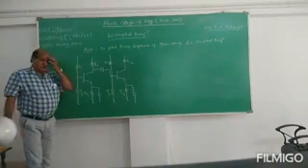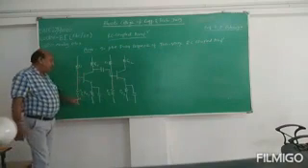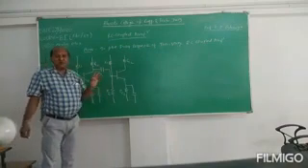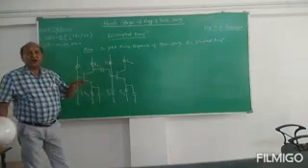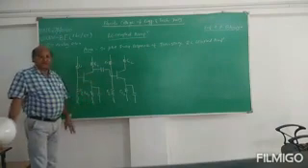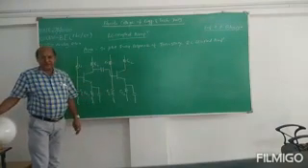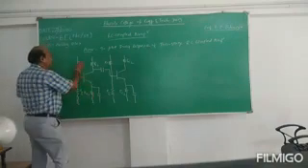So for practical use, R1 and R2, all components may be the same: these two R1 are the same, these two R2 are the same. Or for gain adjustment purposes, you can use different values. The practical circuit which I am using has different values, which I will give you later.